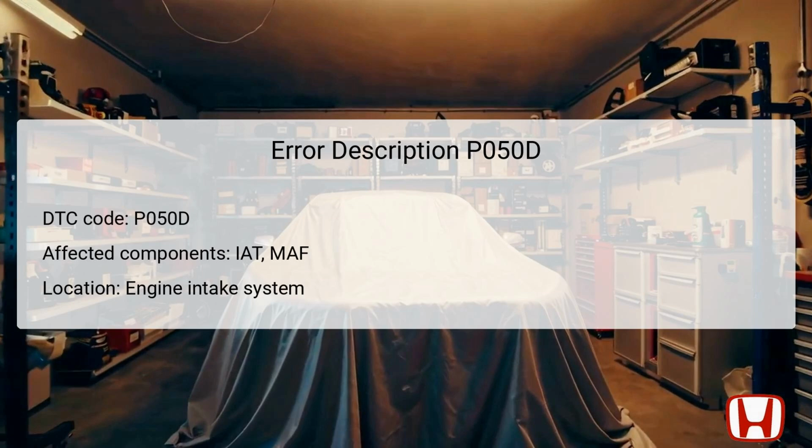The primary components involved include the intake air temperature, IAT sensor, which measures the temperature of the incoming air, and the mass airflow, MAF sensor, which assesses the amount of air entering the engine. Both of these sensors are located in the engine's intake air duct before the throttle body. Incorrect readings can lead to improper fuel mixture, causing idle instability during cold starts.